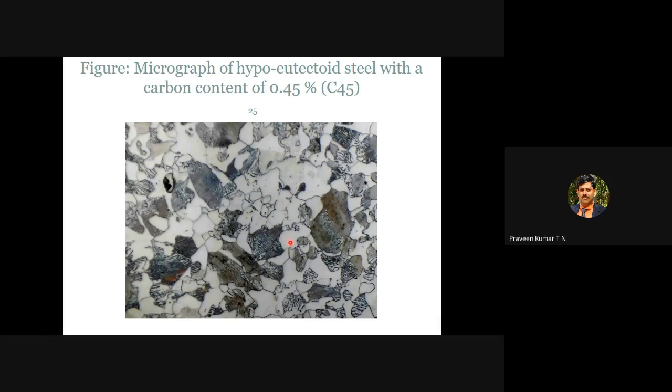Most automotive companies and aerospace companies, whenever they receive steel, will not check only the weight of the steel. A few tons, they will go and weigh it, but that is one part of the checking. Another part is that they randomly pick some steel material and see the microstructure. Based on that, they will accept the complete truckload of steel, otherwise they will reject.